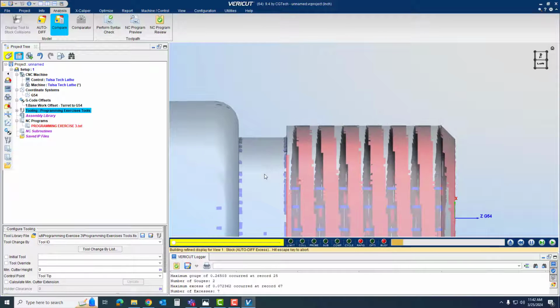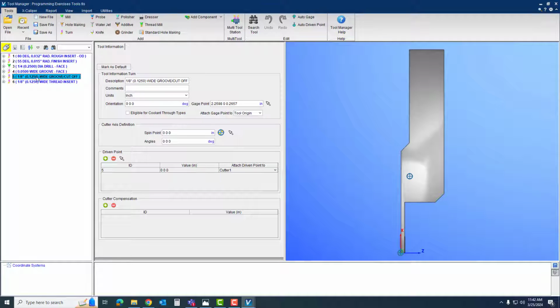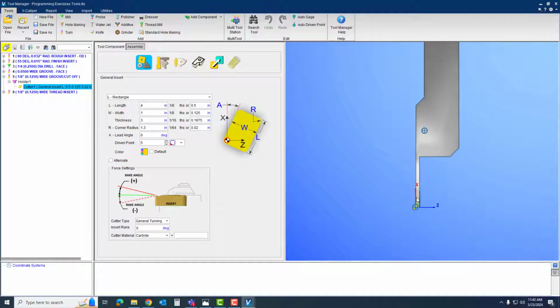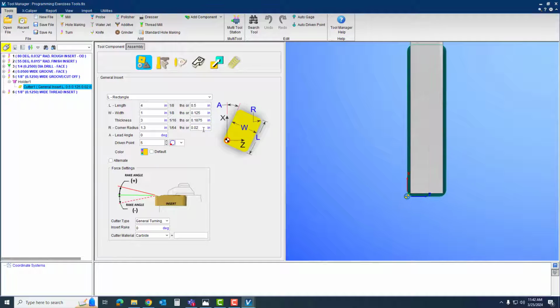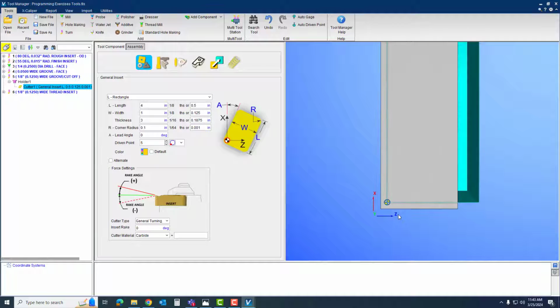Now what I've been running into is when I try to change it to a 0 on my tool list right here, which should be pretty simple. I come up to here and I would just go to the tool nose radius and I change that to a 0. But with this sample library, it tends to mess it up. So if I put a 5 thousandths or even a 1 thousandths on there and I bring this back up, it tends to really want to mess up my tool holder. So just knowing what's happening right here is good, and if you're able to fix it, great. Be sure and let me know.